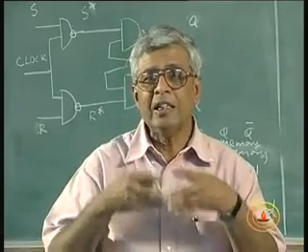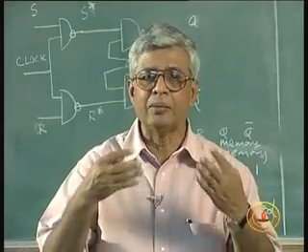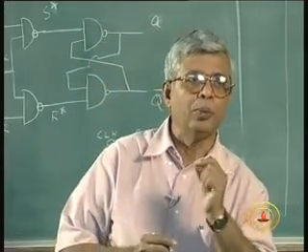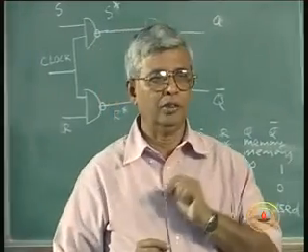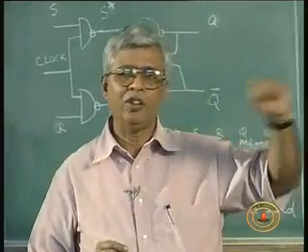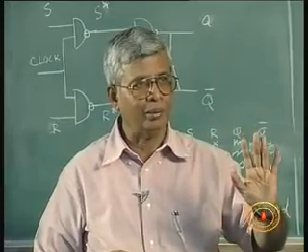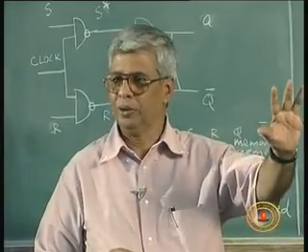This is generally a good practice in any digital system design, in sequential circuit design. It's a good practice not to make changes in the input when the clock is high, because when the clock is high, it can immediately affect the output. Whereas when the clock is low, it will wait for the next clock pulse. Only then it will affect the output.